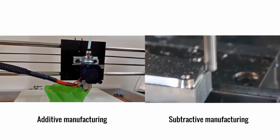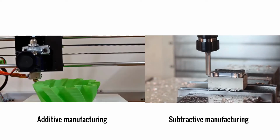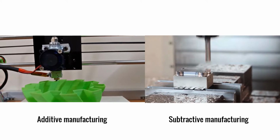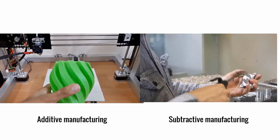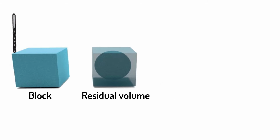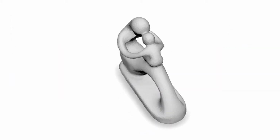Despite the recent popularity of additive manufacturing, such as 3D printing, subtractive manufacturing through CNC machining remains one of the dominant manufacturing processes for high-volume production of finished 3D products. In CNC machining, a cutter goes around a 3D material block to carve off a residual volume to produce a target 3D object. The most commonly applied subtractive manufacturing method uses 3-axis machining, where the cutter moves along 3 degrees of freedom. However, this task is quite involved.